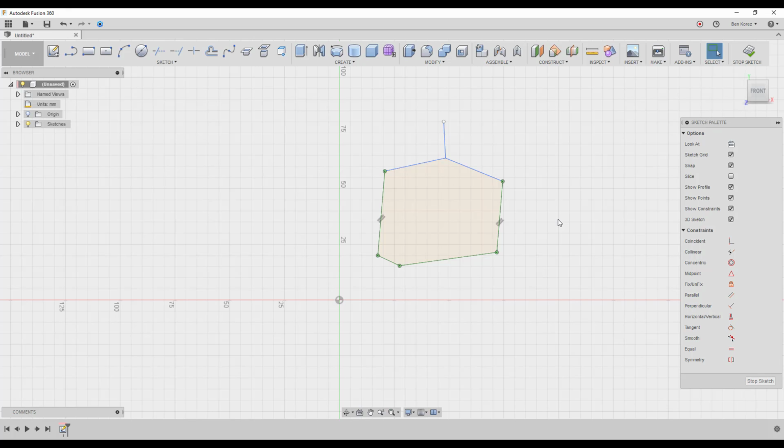Okay, so now in conclusion, constraints are about controlling, fixing or limiting the shape of the geometry and the movement of the geometry in our canvas here, or in relation to other geometries, or in relation to the joint region here.